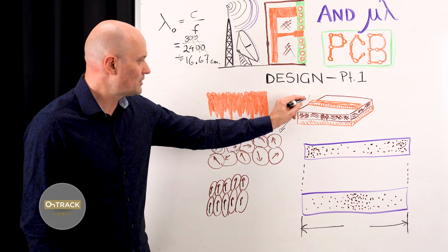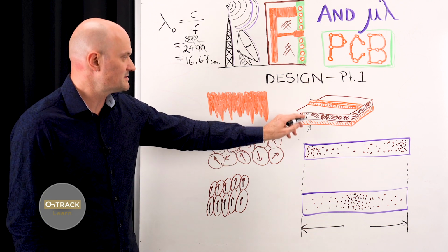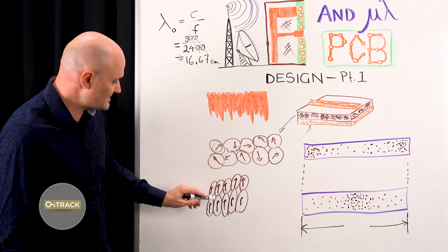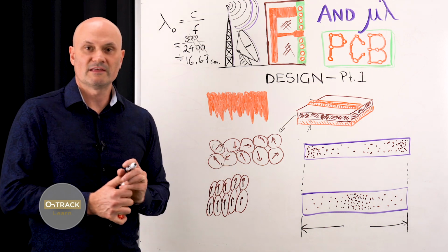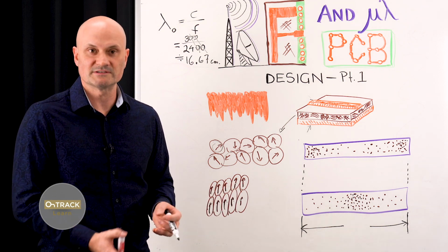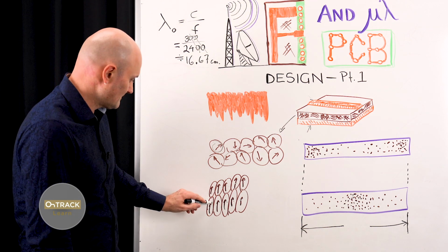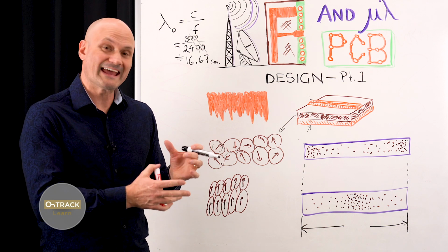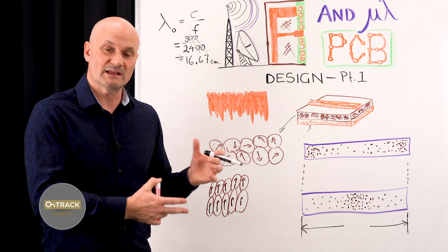And when you put a voltage between two conductors, so the trace and the reference plane is 0, and we have a pulse voltage on the trace, so 3.3 volts, where that voltage exists, we're forcing the molecules in the insulator to align their charge domains, because like charges repel and dissimilar charges attract. And so having a voltage applied across a dielectric makes these charge domains orient themselves, and that's an actual physical phenomenon, and that gives rise to capacitance and what we call displacement current.